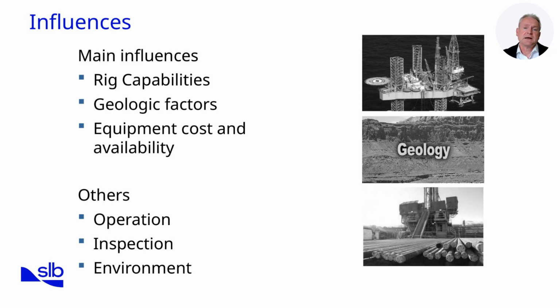Excessive rotary speed can accelerate fatigue, while high tripping rates may induce surge and swab pressures that place additional stress on the string. Environmental factors including temperature, corrosion potential, and the type of drilling fluid also impact performance. According to Mitchell and Miska, 2011, successful design begins with accurately anticipating these loads and their interactions.